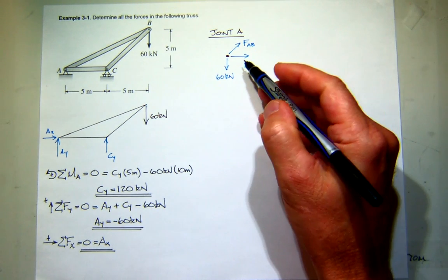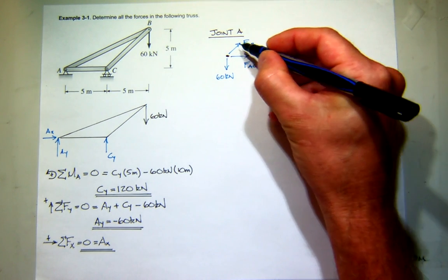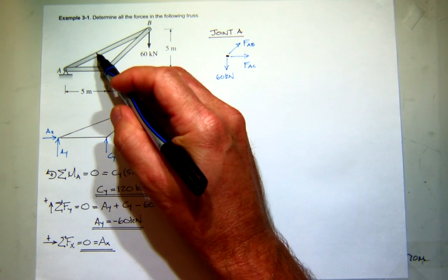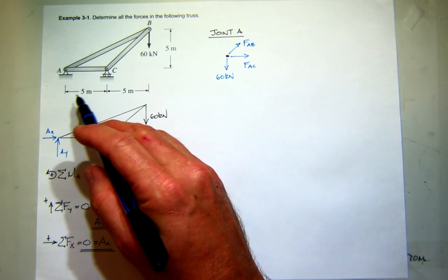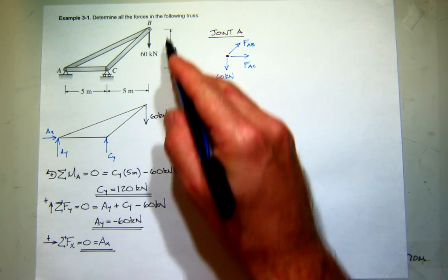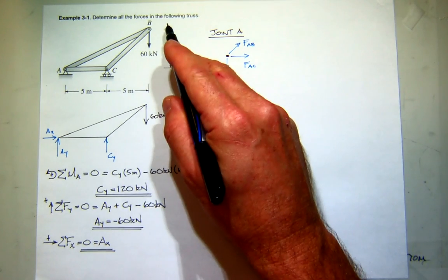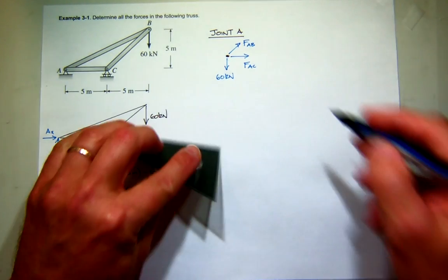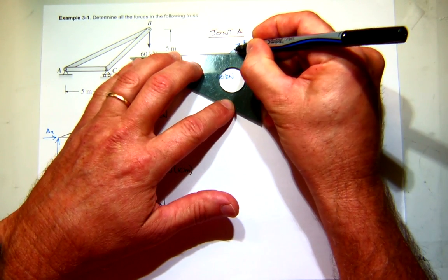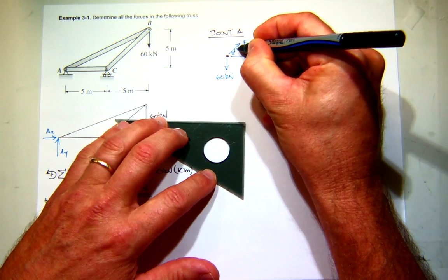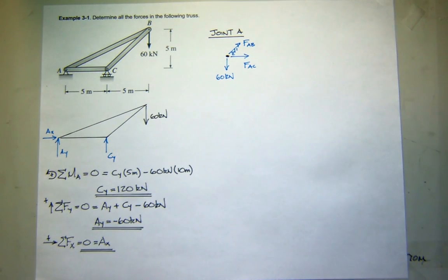And while I'm there, I'm going to go ahead and note what I think this angle here is. It looks like the slope of rise over run, right? So the run is 10, the rise is 5, so that's basically 2 to 1. That's my slope of that. And I'll use that to help me get my X and Y components. Is everybody okay with that?